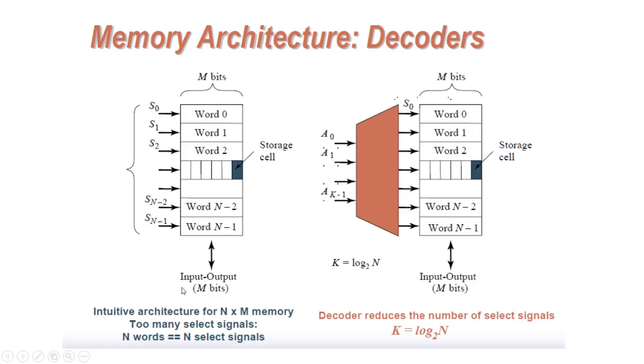And coming to memory architecture, assume that you have to write n number of words. Each word can be of m bits. Assume that it's 8-bit data, and you have around 1024 words to be written onto a particular memory. These are all individual bits where you'll be storing ones and zeros. Assume you have words 0 to n minus 1, totaling n words. And if you want to access a particular word, it can be the 0th word, the kth word, the 100th word, or the 1000th word.